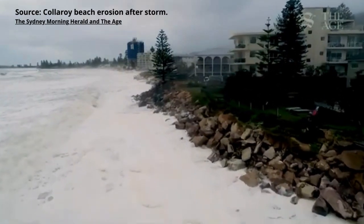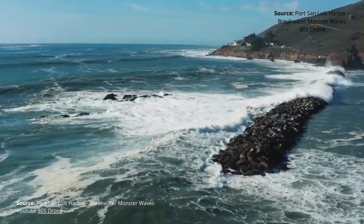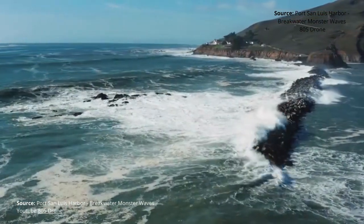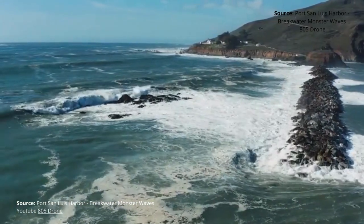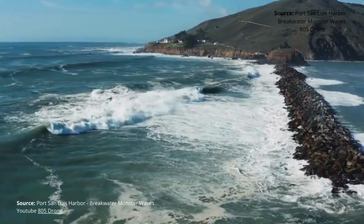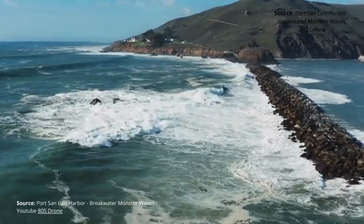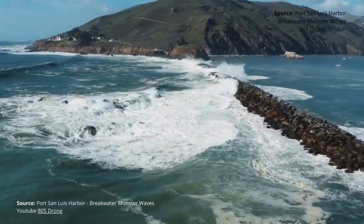In principle, a series of emerged breakwaters or submerged breakwaters reduce the wave heights landward of these structures, and consequently may have the effect of reducing the rate of backshore and dune erosion. However, due to the increase of the water level associated with a storm, the storm surge, the effectiveness of these types of structures in reducing the wave heights under storm conditions is limited.